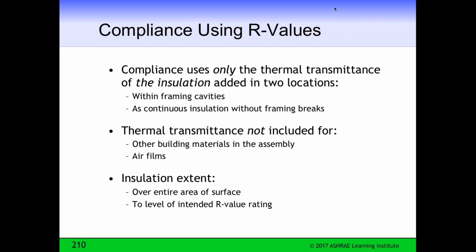So at some time in the past, some members of the Standard 90.1 committee did some hot box tests and determined that the steel stud framing effectively cut the insulation effectiveness by 50% if you only had insulation between the studs. So this led to having continuous insulation outside the studs. And there are building science experts that argue that you should put all your insulation outside the structural members. So it's your choice though.